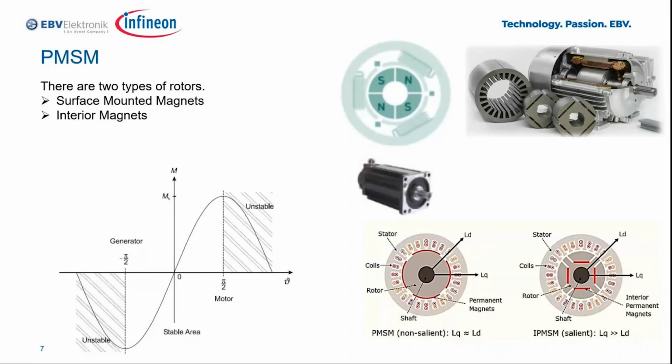other. To develop a constant torque in a synchronous machine, the stator field must rotate synchronously with the rotor because the excitation fields are fixed to the rotor. The field excitation magnets are mounted to the rotor of the synchronous machine.